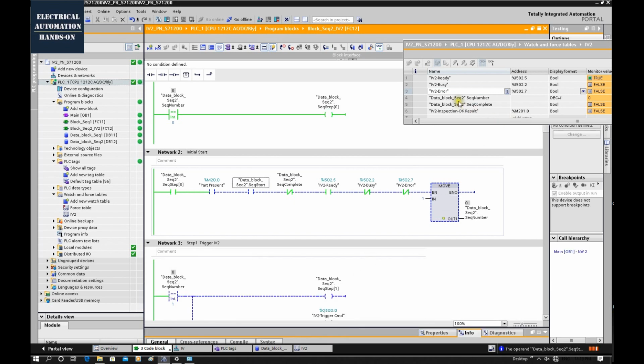So it also shows that using this sequence control, we know whether the problem is in our program or in our device. So it's easy for us to troubleshoot. Otherwise, if I trigger and the camera didn't get the trigger, it's really hard to troubleshoot. The problem came from this busy signal, where I assigned the wrong tag. So firstly, I'm sorry for assigning this busy to a wrong input address. But it's also a good chance to demonstrate that using this sequence control makes it very easy to troubleshoot where the problem is.